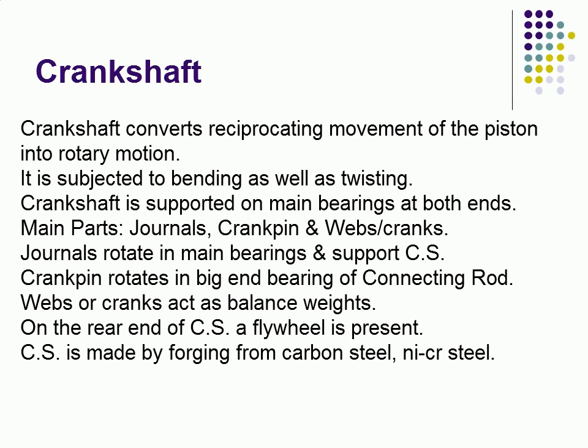The main parts of crankshaft are the journals, crank pin, and webs or cranks. Journals rotate in main bearings and support crankshaft. Crank pin rotates in big end bearing of connecting rod. Webs or cranks act as balance weights. On the rear end of crankshaft, a flywheel is present.